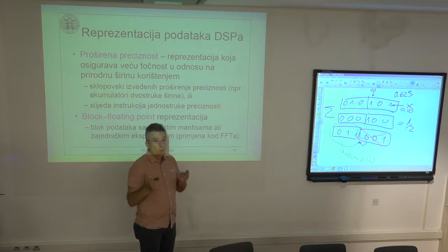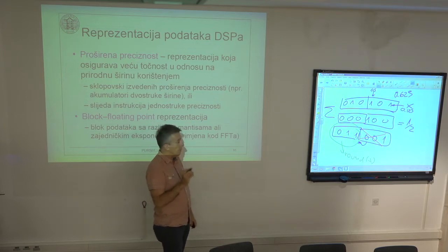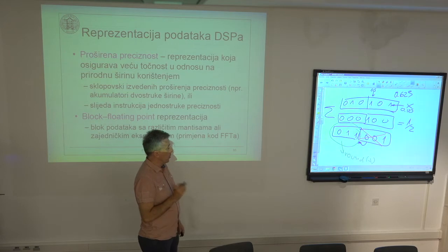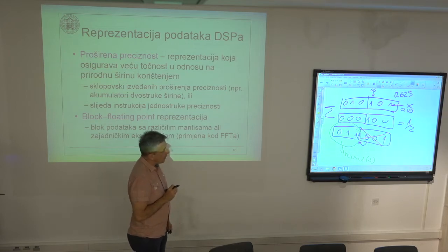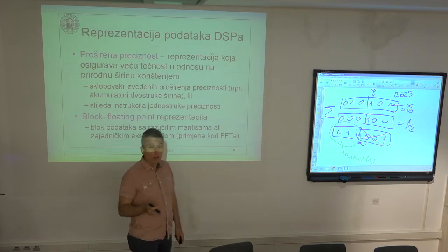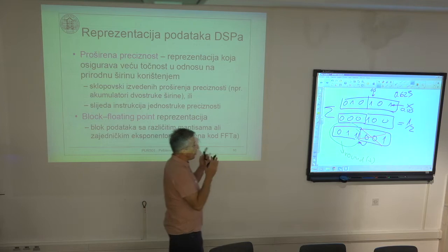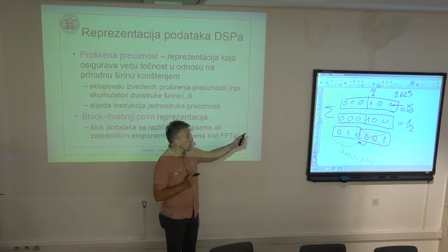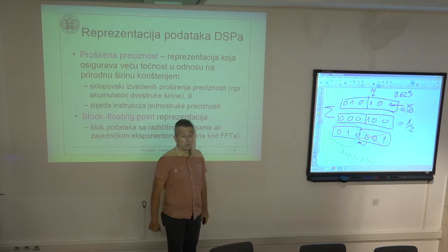If I operate in fractional mode, I always perform this shift to the left by 1 position if the multiplier is operating in fractional mode. After this multiplication and shifting, I add this 1/2 to the lower word and compute the rounded value of the upper word, and I use this as the result of multiplication.